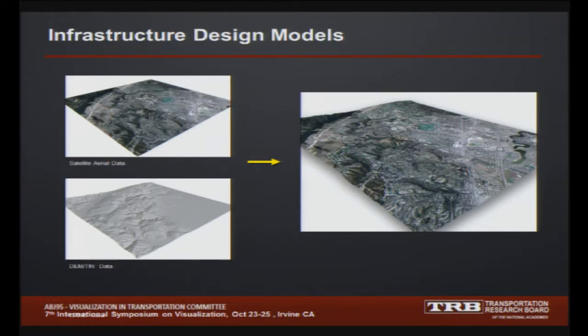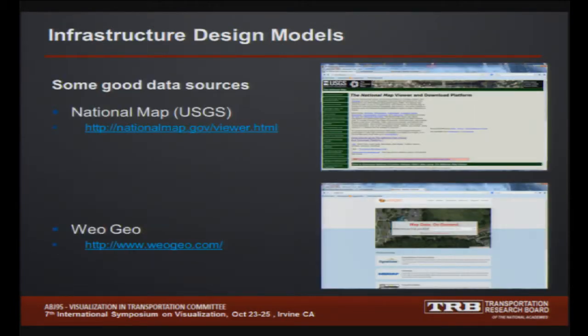The reason we do that is if your aerials match your terrain tiles, you can use those as mapped objects in other products that aren't so geospatially aware. In 3D Studio Max, for instance, I can create a texture map terrain as long as my aerial matches my terrain model. So again, that's our first step: tile out the area, get these aerials and DEMs in place.